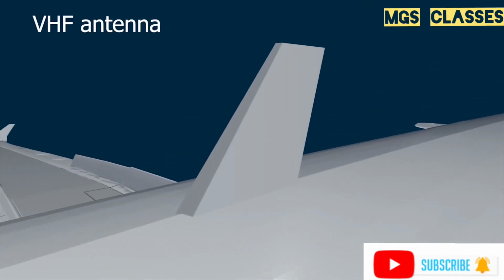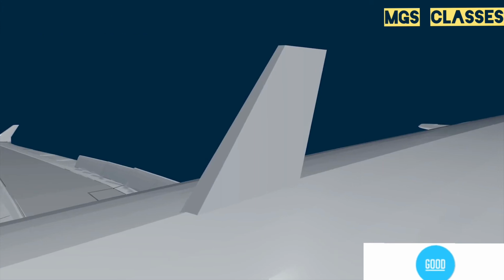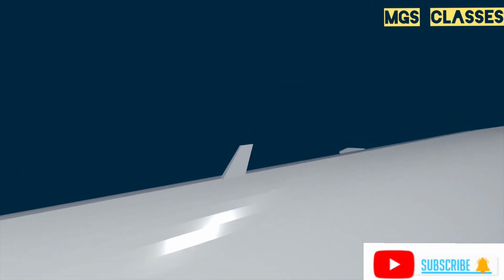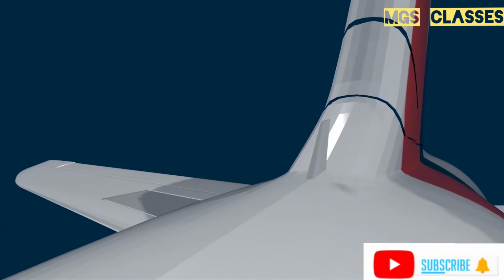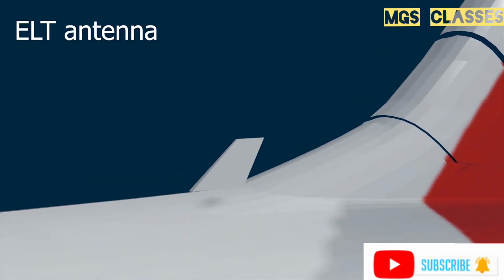The VHF antenna is a communication antenna. It is capable of transmitting and receiving signals in the VHF band from 118 to 156 MHz. The ADF antenna. ADF stands for Automatic Direction Finder. It is an aircraft navigation product that automatically calculates the relative bearing of the aircraft to the radio station. The ELT antenna. ELT stands for Emergency Locator Transmitter. In the event of an aircraft accident, these devices are designed to transmit a distress signal on 121.5 and 243 MHz frequencies.